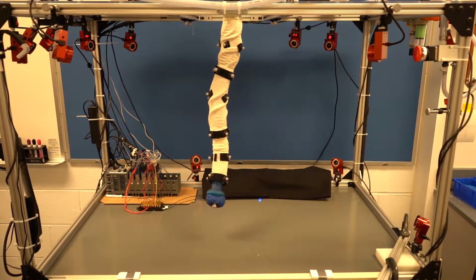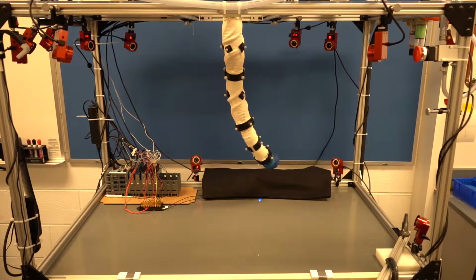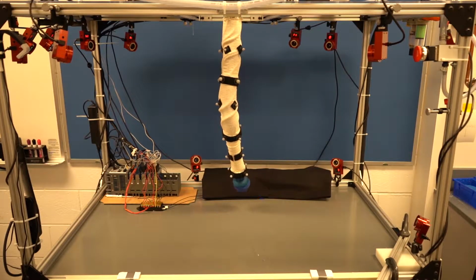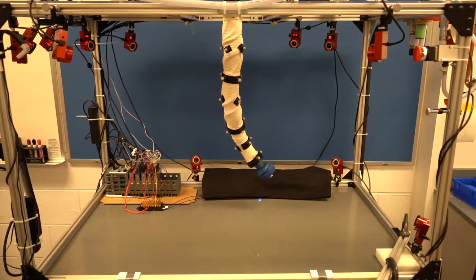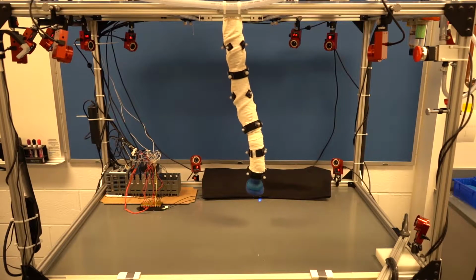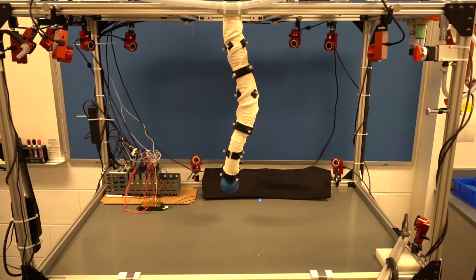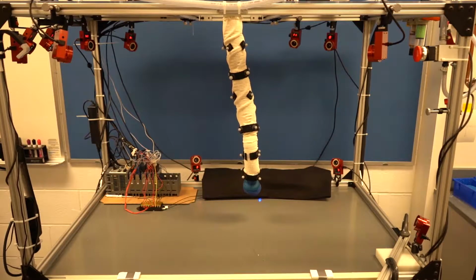In this work, we present a data-driven approach to identifying soft manipulator models that enables consistent control under variable loading conditions. This is achieved by incorporating loads into a linear Koopman operator model as states and estimating their values online via an observer within the control loop.